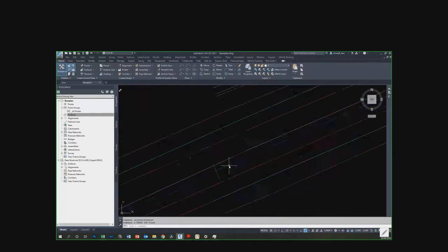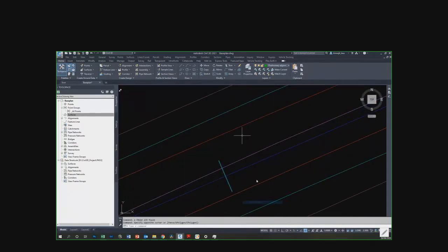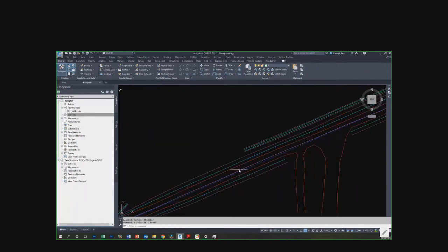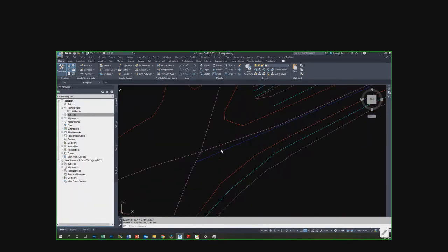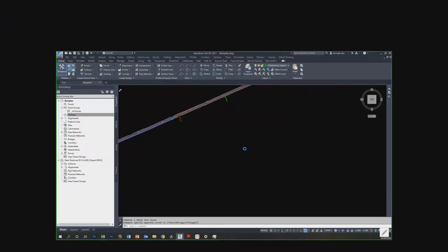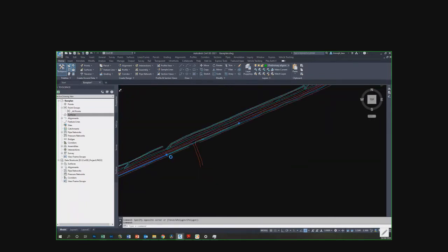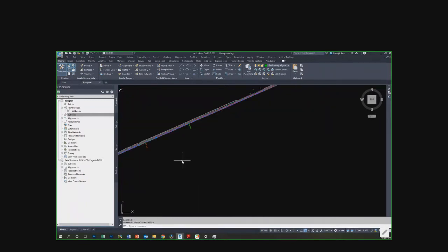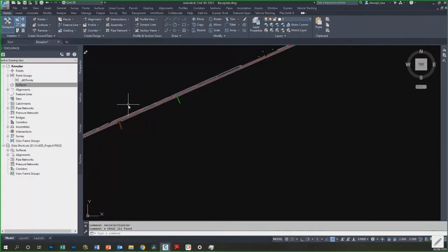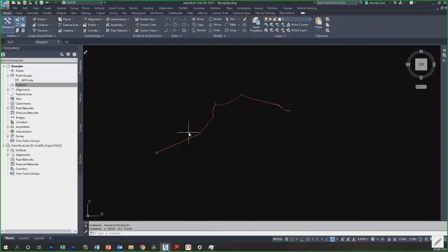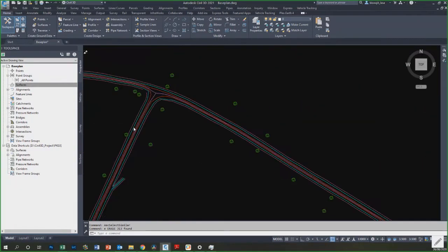You need to clean up all the drawings whichever is not having a Z value. This one is the alignment which is created by the surveyor. You need to delete it all. And remember, this is the case for all the surveys. Whenever you do surveys, the surveyors do their cross-checking parameters and then give you the data. So you need to remove all these design parameters, whatever has been already designed by the surveyor. Check your data before starting up the design.